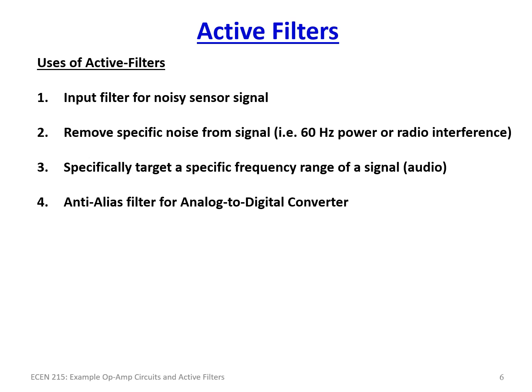Another common example is if you've ever used a timing light to time an engine. The timing light is set to the frequency of the rotation of the engine. So if your engine is rotating at 1,000 RPM, the timing light is firing at 1,000 RPM, and it makes it look like the flywheel on an engine is standing still. And if it's not standing still, you have to make slight adjustments to raise it and back it off and things like that.